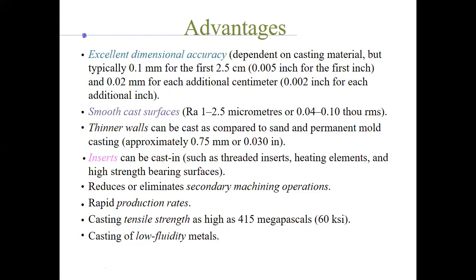The fluidity is basically the ability of material to flow, right? So if a material is having a property that it doesn't offer much fluidity, flowability, then for such cases we can go for this type of casting because that plunger is able to make up for that loss of fluidity, or the low fluidity problem that we have.